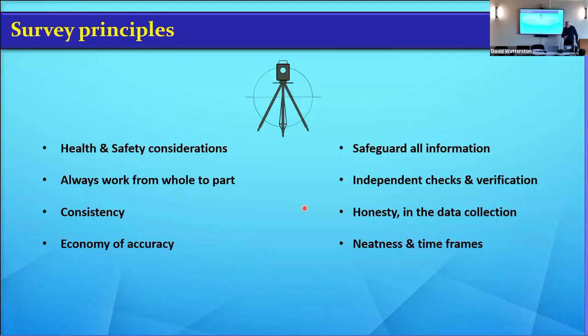But anyway, we surveyed these things, and because we'd been booked on a flight to come home after 6 months, I was doing a whole bunch of leveling to prove our survey work. And because there was loads of it, I didn't have a chance to reduce it all to make sure it closes. Because if it doesn't close, you need to redo it. And I honestly, hand on heart, was sitting in the plane coming home to the UK, reducing my levels.